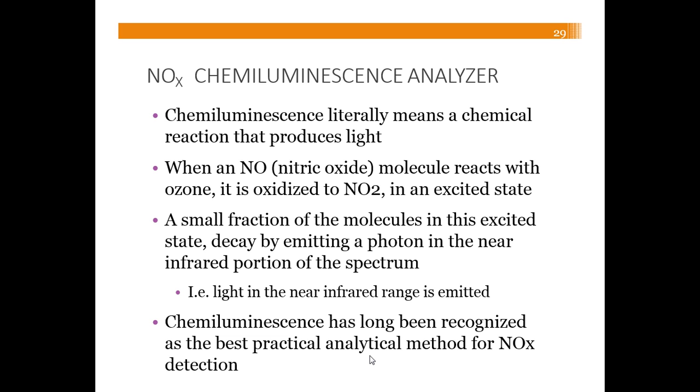So the first one we're looking at is our nitrogen oxide chemiluminescence analyzer. From your glossary, you should recall that chemiluminescence literally means a chemical reaction that produces light.